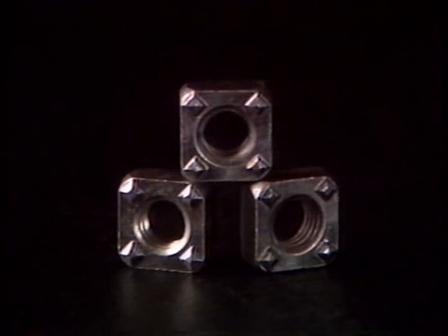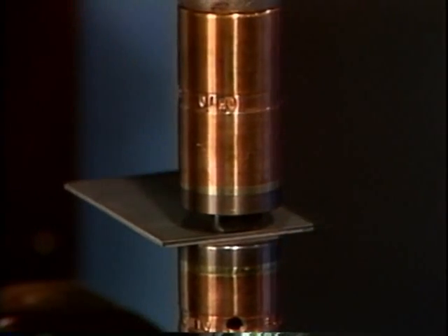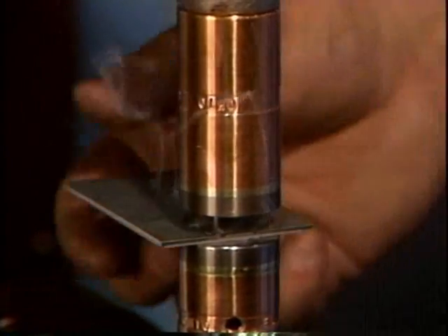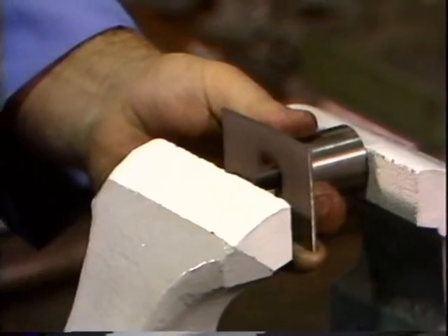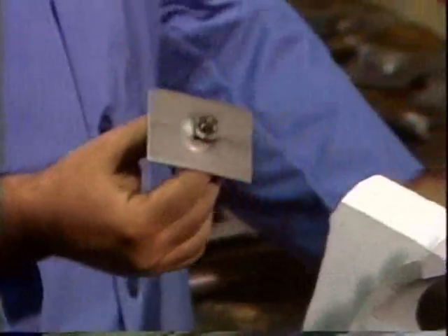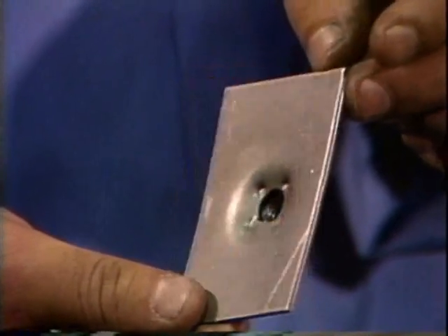Our WS 3301 3/8-16 square projection weld nut has 4 uniform pyramid projections that provide proper seating and positive welds. Thread engagement is enhanced by a countersink on each side for easy engagement. In a direct push test, the WS will pull weld nuggets from the sheet material.